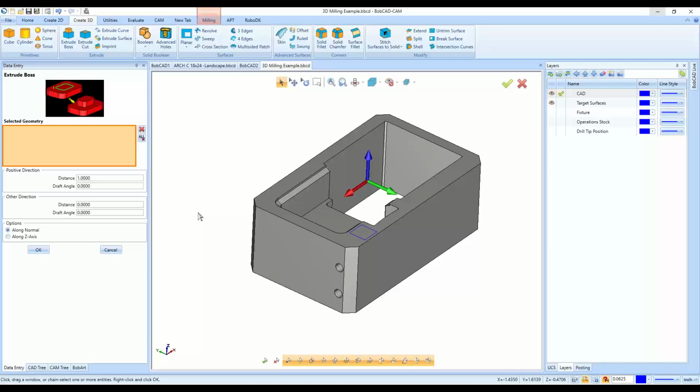There are a few other shortcut keys here for hiding the surfaces, for showing wireframe, for different options like that. So T is for transparent, so you can see the holes in here and any other openings here in the solid model.